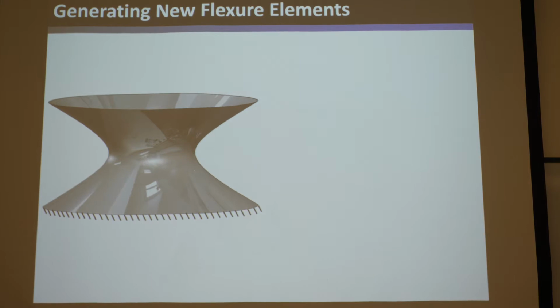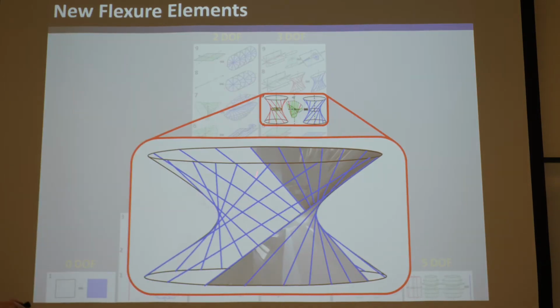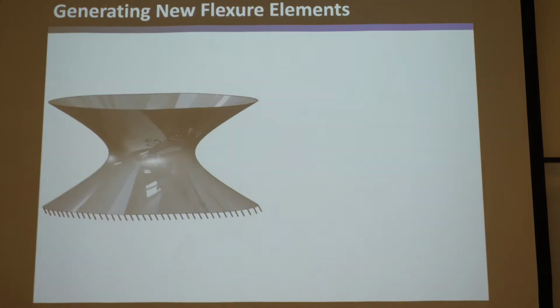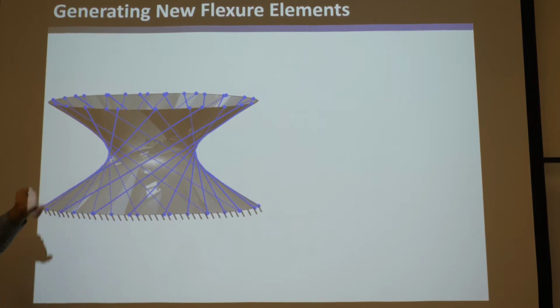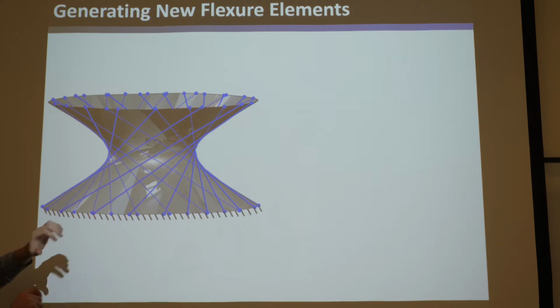Would it move with the same freedom space as this guy? Well, hopefully you can visualize no. The question is why, though? It lies on the exact same surface. Well, the reason is because, first of all, is this even a parallel element? Well, sure it is. You could directly connect this body and that body on top with all blue lines that pass through the entire surface, and you could fill the whole thing blue. So it is a parallel element.